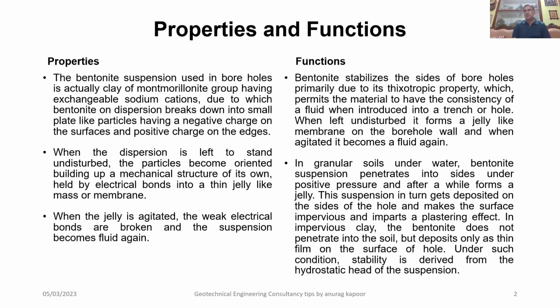When this dispersion is left to stand undisturbed within the borehole, the particles become oriented, building up a mechanical structure of its own held by electrical bonds into a thin jelly-like mass or membrane. When this jelly is agitated, the weak electrical bonds are broken and the suspension becomes fluid again.